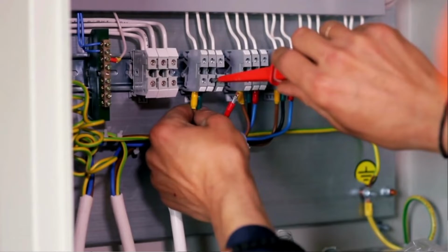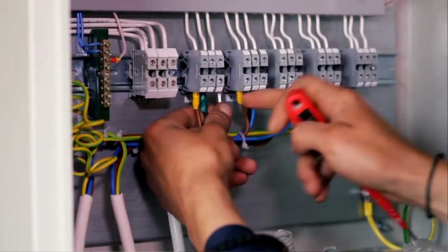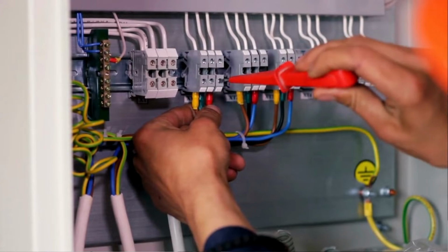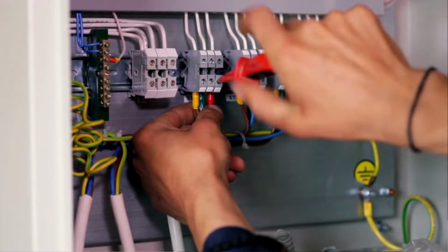A qualified employee required to cross the restricted approach boundary must be protected from unexpected contact with the conductors or circuit parts that are energized and exposed. Qualified employees should have the knowledge and the ability to avoid unexpected contact with an exposed energized electrical conductor or circuit part. A complete and authorized energized electrical work permit is required, however, before employees are allowed to work within the restricted approach boundary, unless a qualified person is provided with and uses appropriate safe work practices and PPE in accordance with the rules and regulations of NFPA 70E under any of the following conditions.